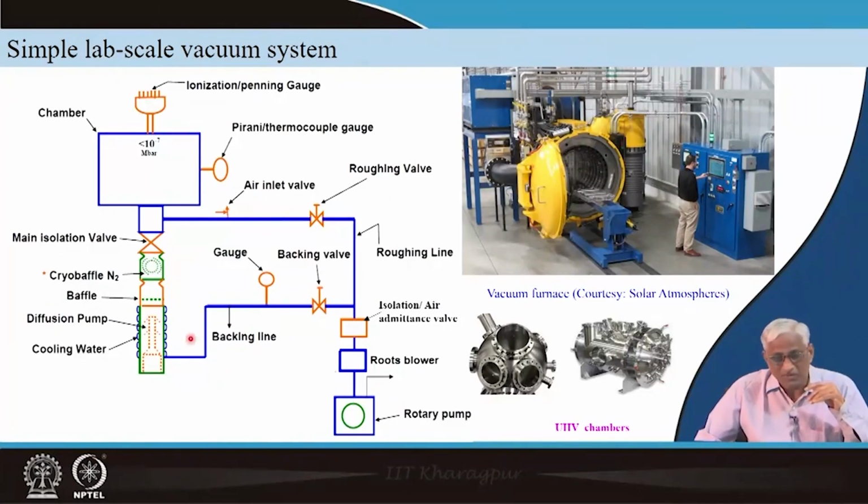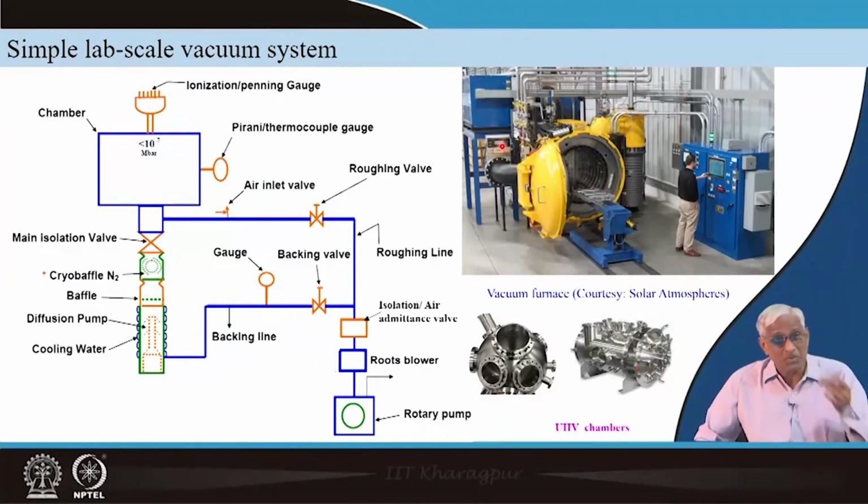Similar system we will be facing when we are dealing with a vacuum metallurgical furnace. You can do 1-to-1 correspondence here. This is the system, this is the system. These are gauges, valves. Similarly, pumps, diffusion pump, backside there will be rotary pump, roots blower, but with a bypass connection, because initial evacuation you have to use roots blower to boost the pumping, and then later you switch off, otherwise lot of electrical power requirement.